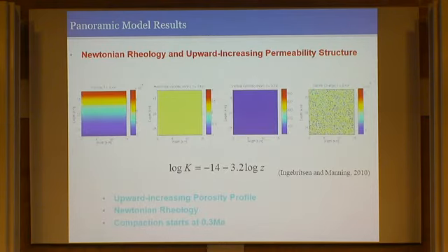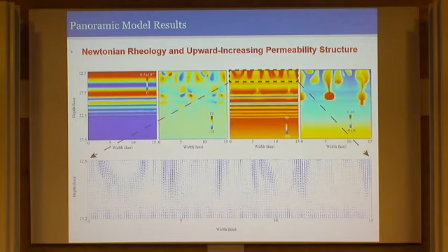So this is the last case. The only thing is porosity and permeability are no longer homogeneous initially. We initially prescribed this empirical relationship from field observation, field measurements, and then still let the system be able to compact and then see the effect of compaction. So still let convection happen first, and then when it's fully developed, we let the system compact.